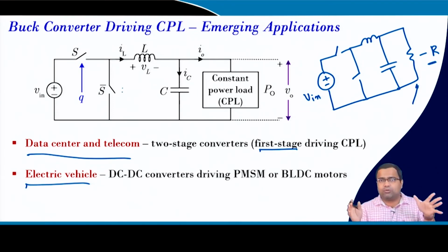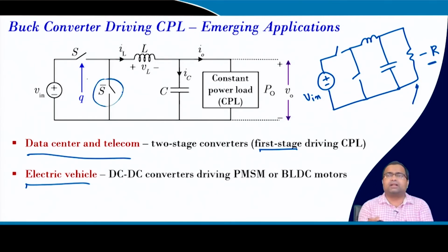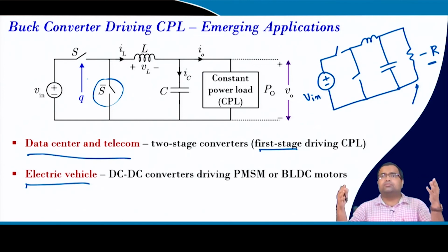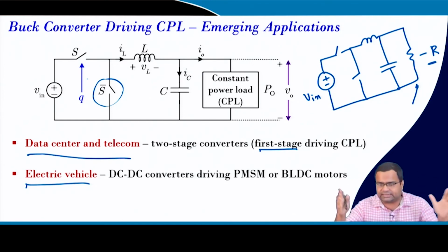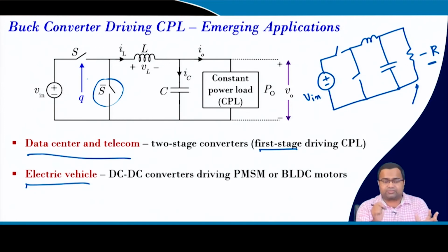So, if you run this DC-DC converter in open loop, in general the open loop converter will be unstable. The oscillation will keep on growing, and if we apply a diode like a conventional buck converter, then it will get stuck because of the zero current, and it may lead to limit cycle oscillation. There is extensive research on that, but I am not going into that. In this constant power load case, our tuning method can also be applied, both for stabilizing the converter as well as to get the fastest response.